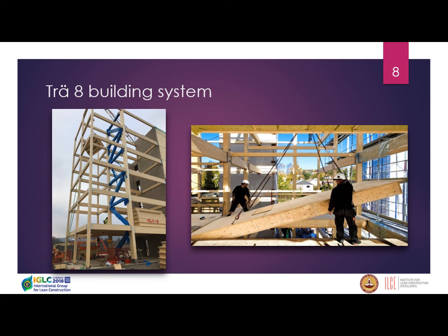these are the structural components like column, beam, and trusses in blue. And these are the elevator shaft and staircases with the concrete. These structures are connected with steel connectors, and intermediate floors are there along with wall elements. So it's completely built with mostly timber, with concrete and steel components.